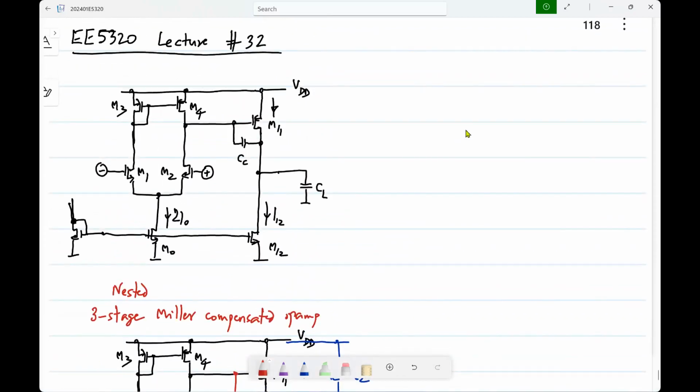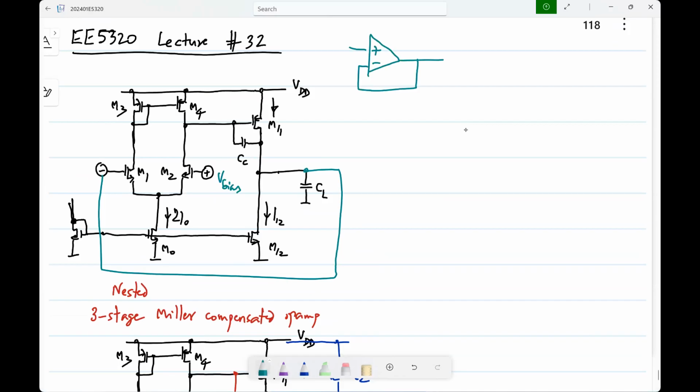Now, how do these op amps get biased? Because of course, if you leave it in open loop, it is not going to be biased correctly. And in any case, especially with random mismatch, it's guaranteed that the output will be near the upper or lower saturation. Okay. So again, I'll consider unity feedback. The feedback need not be unity, but let's say I connect it up like that. Okay. And then this is at some Vref or V bias. This is equivalent to that one, right?